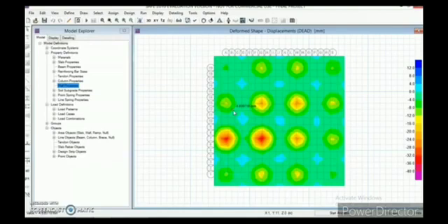You can see the displacement values of the different slab regions are displayed here. Now the different displacements are being displayed here. So after this, what we need to do is check our punching values, and you can also check the displacement values at every place. And now go to the display menu.